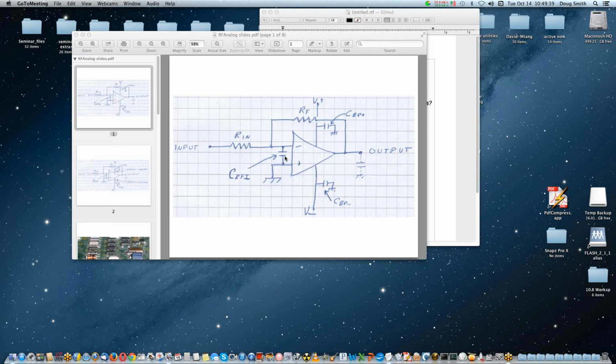Well, let me do that. What happens is if you plot the gain and phase of the feedback loop, it does reduce the gain and phase margin. And if you put a big enough capacitor there, and it might not have to be that big, a few hundred picofarads might do it, you can cause things to oscillate in band, somewhere in the audio band, or up to 1 gig, somewhere in the unity gain bandwidth range.